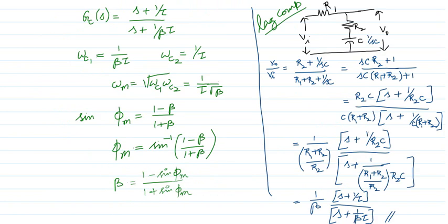It's very similar to what we have seen for a lead compensator, the same thing. So here omega C1 is 1 by beta, omega C is this term. The maximum phase angle occurs at omega m, which is the square root of the product of the two corner frequencies. I get this value, and similar to that, there we got phi m equal to sin inverse of (1 minus alpha)/(1 plus alpha). In place of alpha I am putting beta here, right? Remember, alpha is less than 1, beta is greater than 1. Okay, and this circuit is a lag compensator circuit.